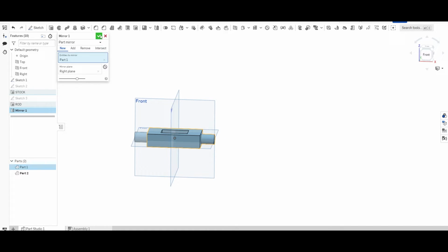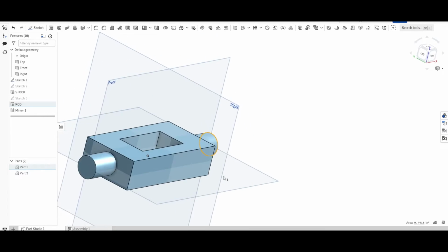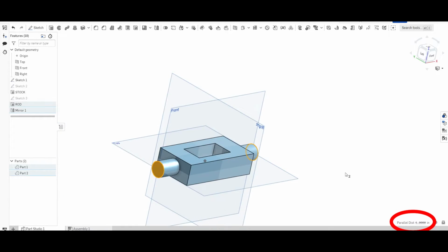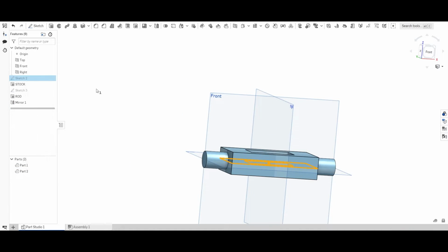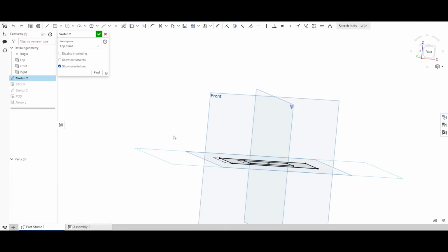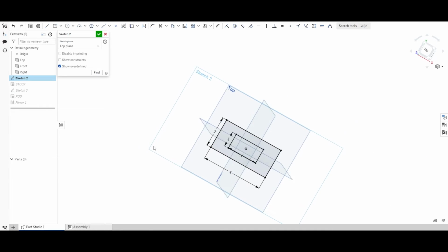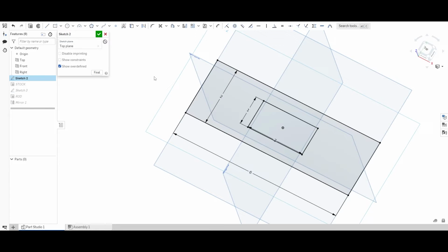Here I mirrored the rod across both sides, and I'm going to show you here. If I measure this on both ends, you'll see down in the lower right hand corner it pops up that it's about 6 inches wide. Now what if someone comes to you or you're designing something and you realize I have to change this to 8 inches wide? How can I easily do this? Well, you can go back into the sketch for the original model. You can go in here, you change the one dimension from 4 inches here in this case, and you can change it to 6 inches, and this will change the model overall across the whole model because you designed it from the mid plane.